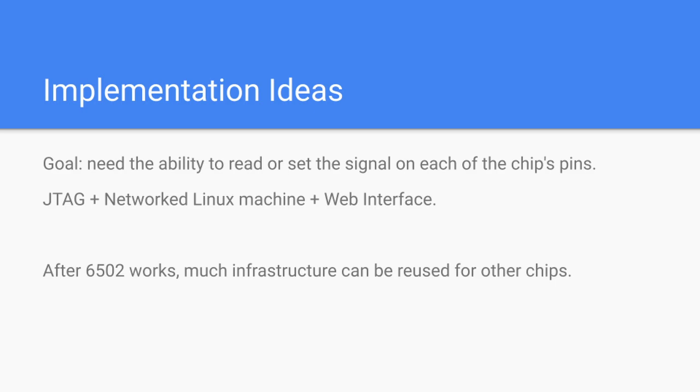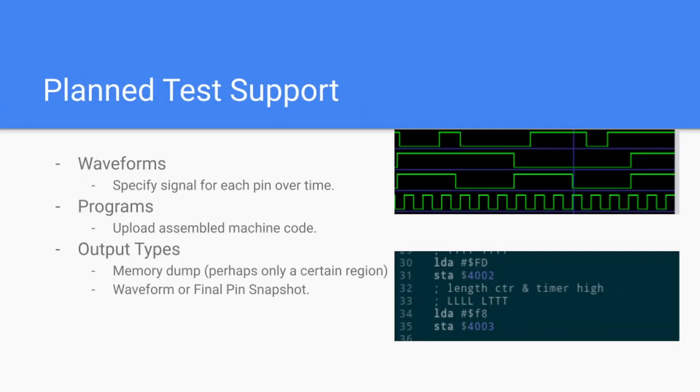The Linux machine that it is connected to will be running a web server that allows people to interact with it, and will also contain a driver to communicate with the JTAG hardware, which talks to the chip. The web interface will let you see which chips are available, and also specify and run the tests. Right now, I have 2 types of tests that I want to support with this system.